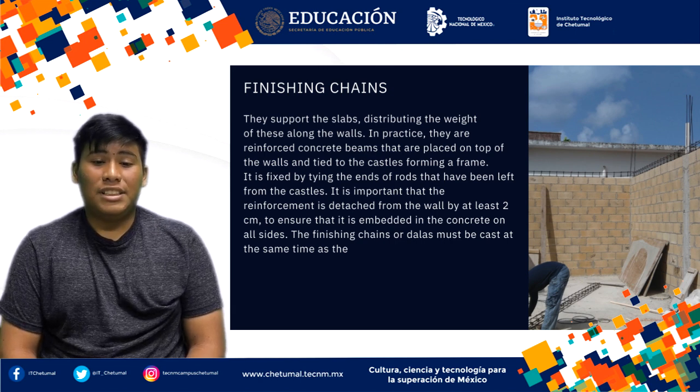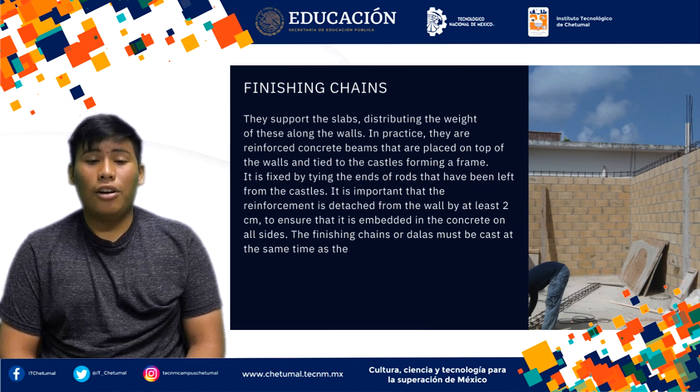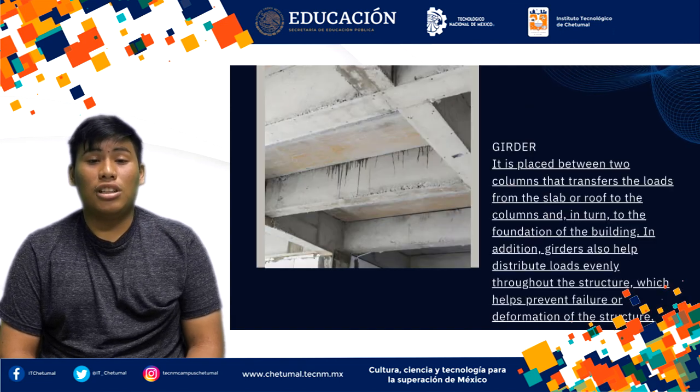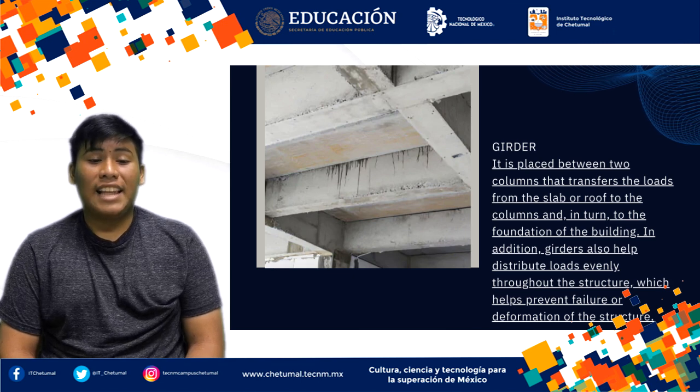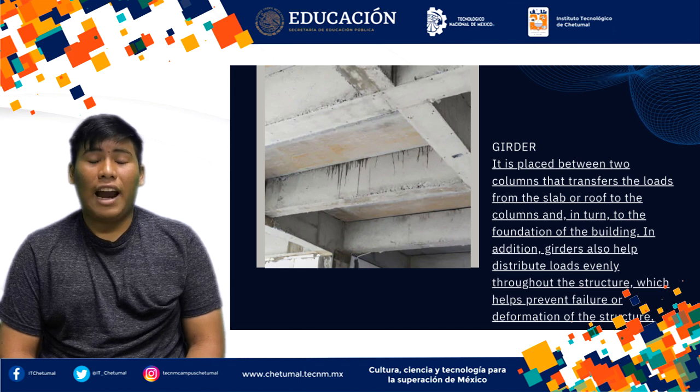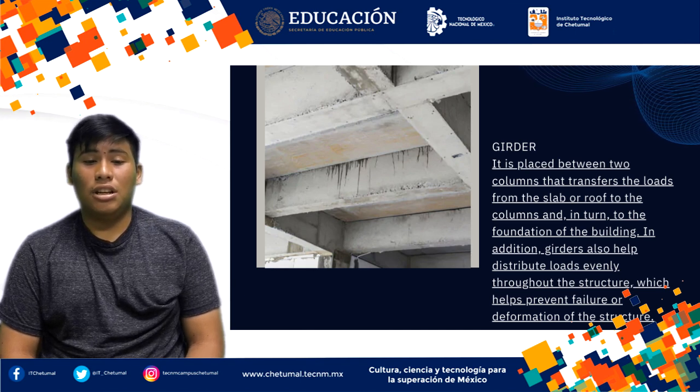The steel deck slab is generally used in industrial or commercial constructions. It consists of corrugated steel sheets that serve as a base for the concrete that is poured on top. Its advantages are quick installation, structural strength, and flexibility. It is lighter compared to the other slabs. As for its application, it is ideal for high-rise buildings or industrial warehouses, where strong yet lightweight structures are required.